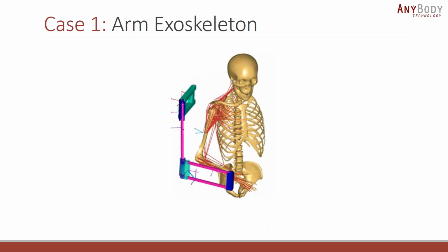So the exoskeleton that they designed looks something like this. It was a passive gravity compensating exoskeleton. And for those of you who are familiar with gravity compensation devices, the whole idea is to place some strategically located springs in your mechanism so that these springs effectively cancel out the feeling of gravity. So in a way, it assists your body to move against its own weight.